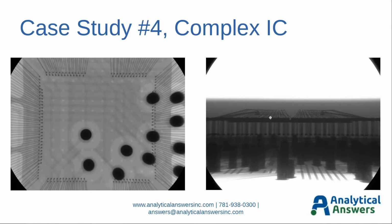So here's a side view X-ray image of that same integrated circuit to show that, in fact, this particular integrated circuit here is facing up, and so we want to come in from this top direction. It may be the case where this was facing down, so we need to come in from the bottom of the package to expose the circuitry on the integrated circuit here within the package. So again, it's important that we understand the orientation of that device.